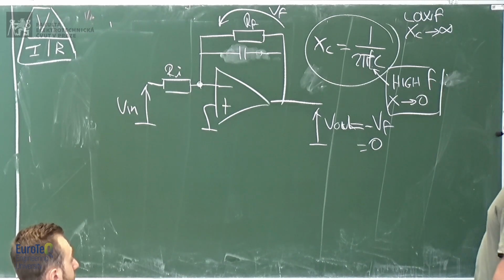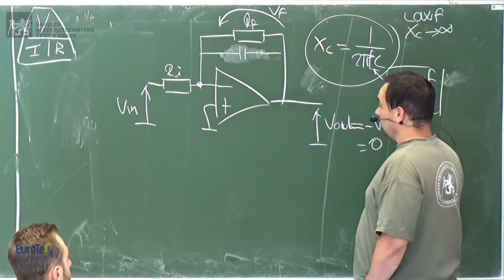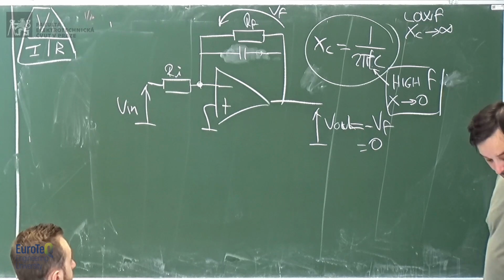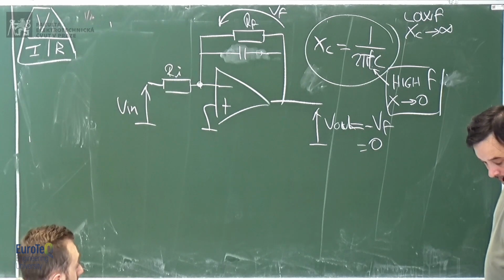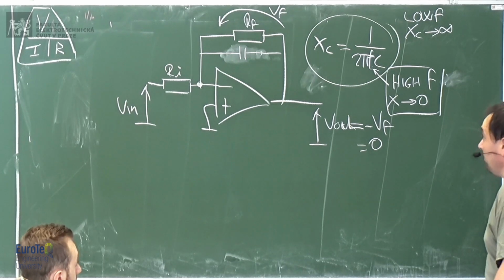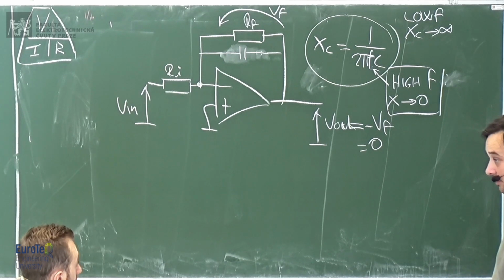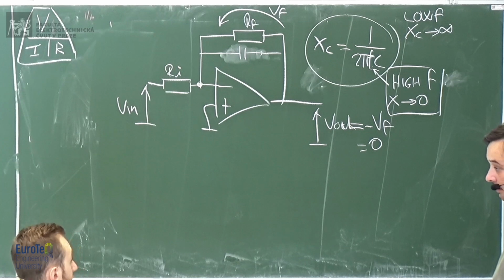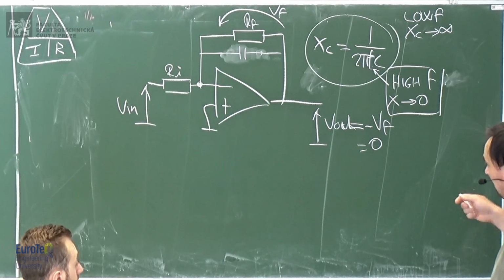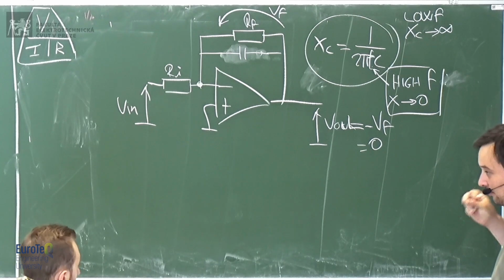What frequency would I put in the equation of XC? Sorry? Okay, so there are frequencies near the 1 megahertz range that we want to attenuate or get rid of, right? So you have to make your calculation with the resistance and the capacitor. Well, couldn't we just put some frequency value in XC and then we know when XC will start? I don't have on the tip of my tongue how to calculate it.